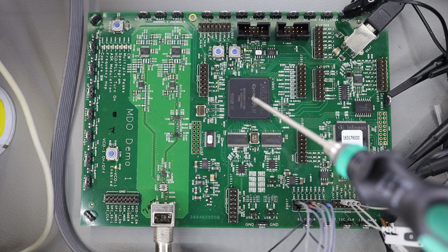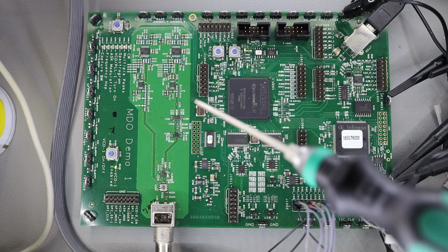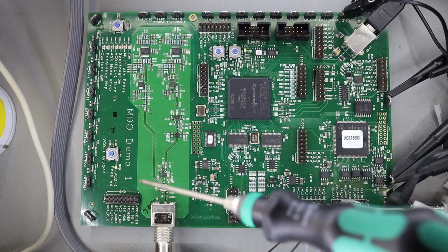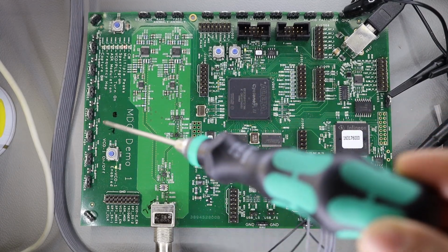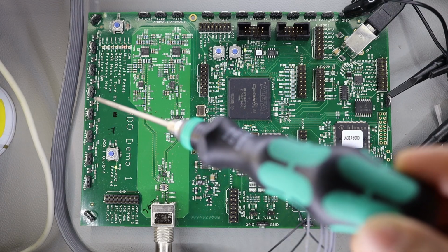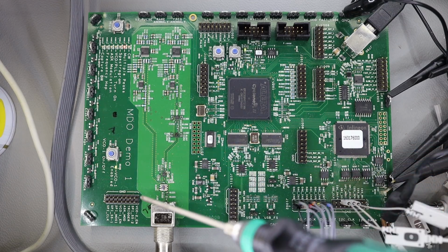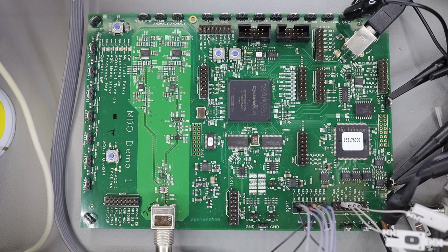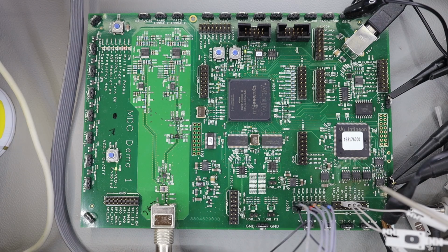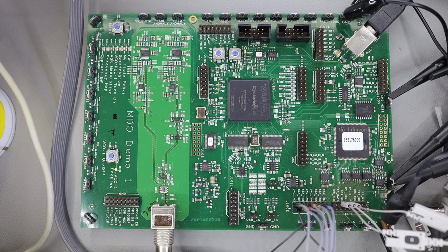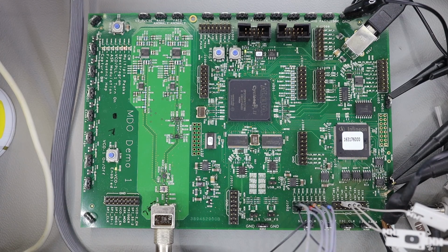This FPGA controls quite a bit of these signals. On this area you have the RF section, and some of the VCO, PLL, and ASK modulation stuff is available there. So right now I'll set up my oscilloscope to decode SPI, and I'll show you how to set up a signal and what to expect and what to watch out for.